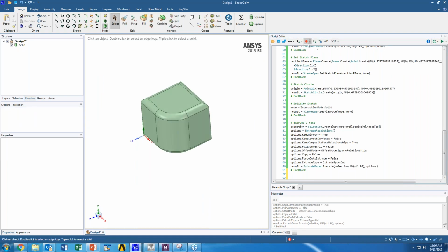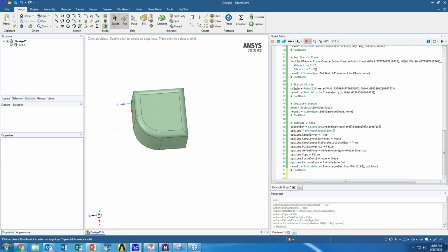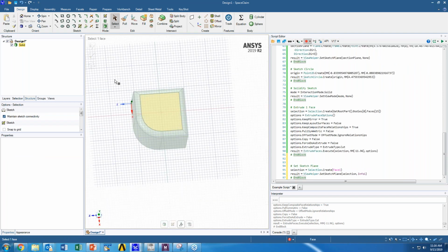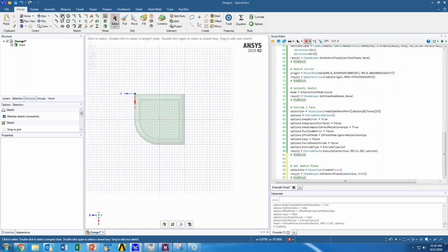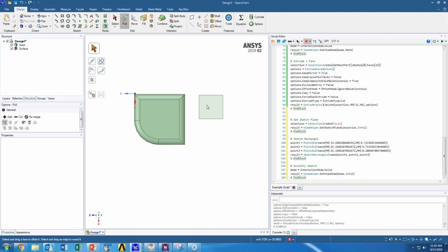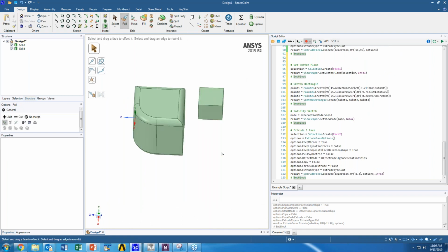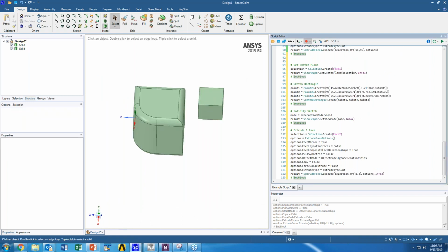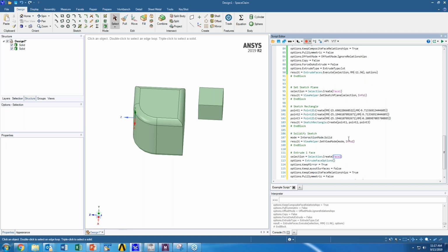So I have my block, my record button is on, and I'm just going to create a new object with smart variable showing. You can already see in the window below the behavior I'm talking about, where with smart variables, you're creating these face1, face2 variables that are pink, which are variables associated with the index of the given part.